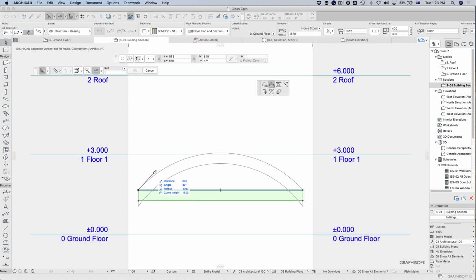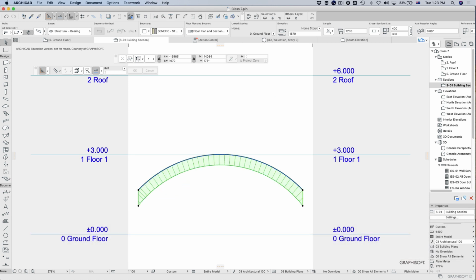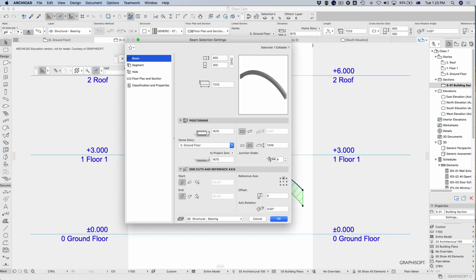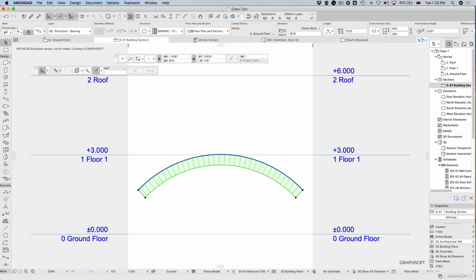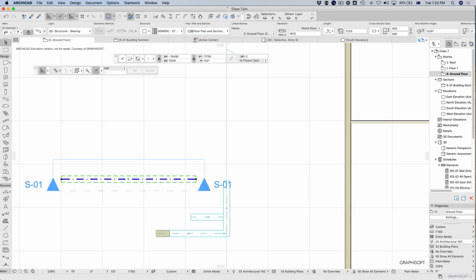So I want to go up from this end, and I want to go at an angle of 45 degrees. That means it's going to be leaving this point here at 45, and then it's going to curve around. In theory, it should be arriving there at 45 as well because the 2 points are level. Now yes, I can do things like have square ends on both ends. It's like as if I just bent that entire beam, which, let's face it, is going to be pretty tricky. But you'll notice now that when I go to the 2D view,